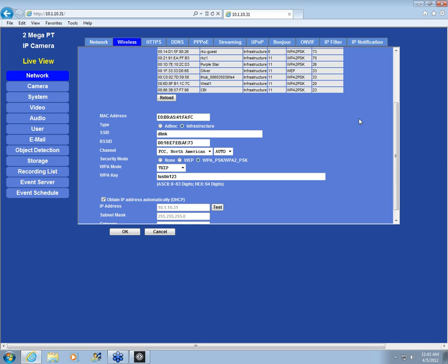You did a demonstration on the wired IP cameras where you could use a dome camera with pan and tilt. You demonstrated one camera. On this software, how many cameras can you use with pan and tilt? Well, you can use every camera as a pan and tilt. But it's not like an address like analogs where it's RS-485 where you have a maximum of 64. Okay, so every camera is all data from there.